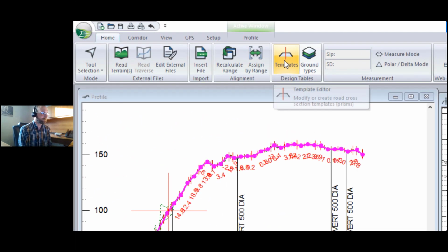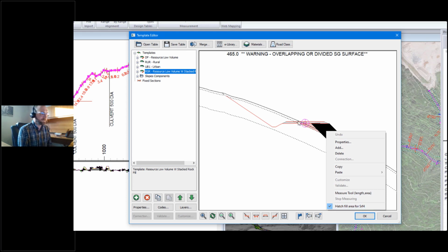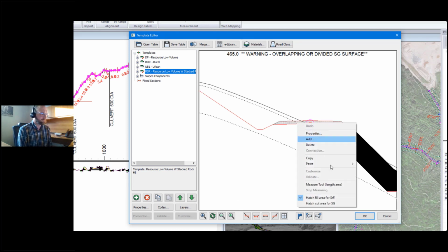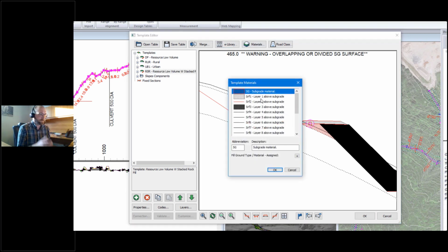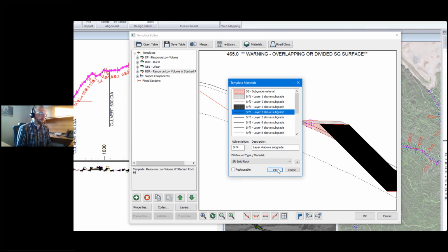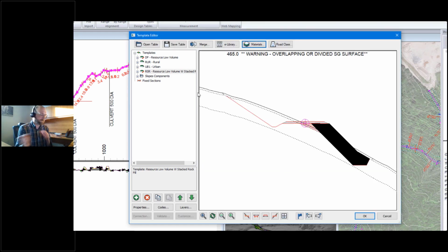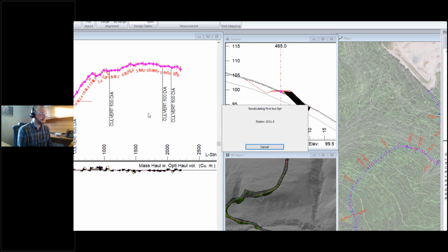It's sometimes not intuitive. And for that other example where I use that keyed in rock fill template, well, those other layers, be it the surfacing layer or that surfacing layer 4, I can assign those into my materials. So now, instead of just being tracked tabularly as its own entity, that's going to be incorporated in my mass haul diagram.